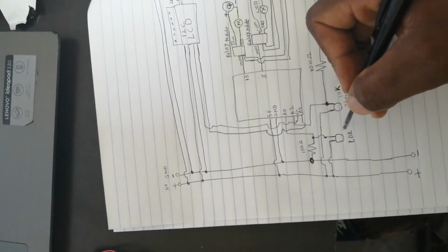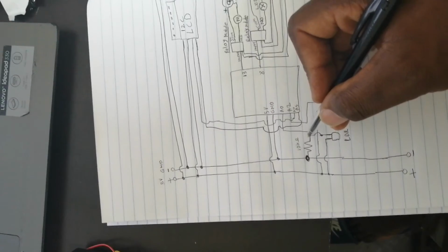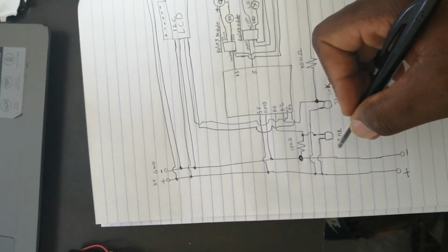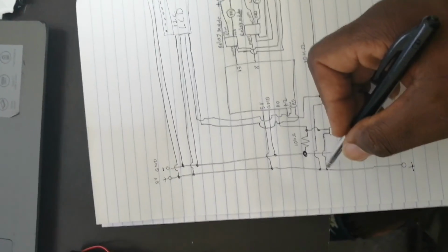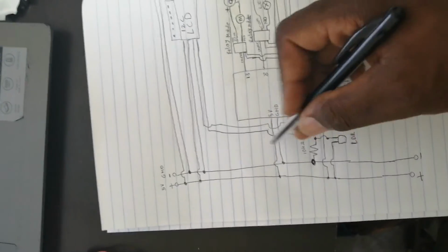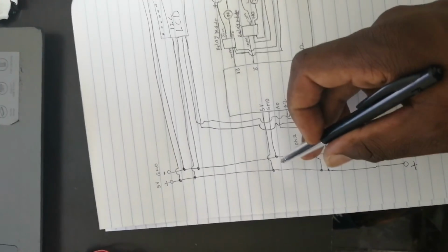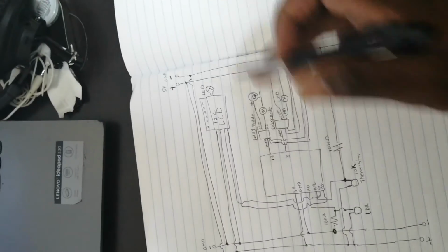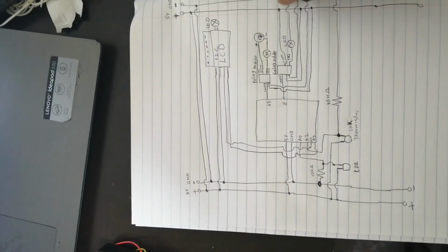And on the LDR, the same thing. Here you have a junction again, the other one going to ground, the other one going to A0, and the LDR's other leg is connected to the 5 volts, which is supplied by the Arduino. So here's the 5 volts coming from the Arduino, connected to both sides of your breadboard. Yeah, so basically guys, that's it.